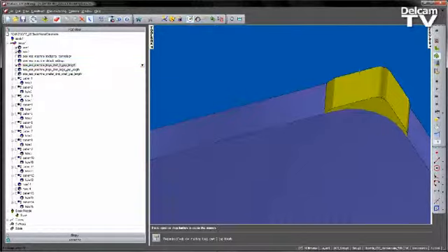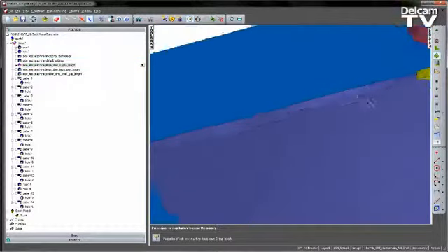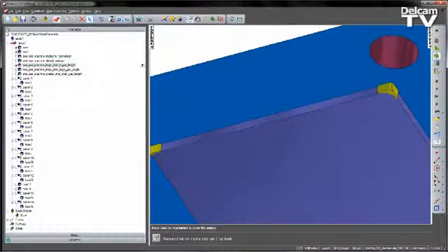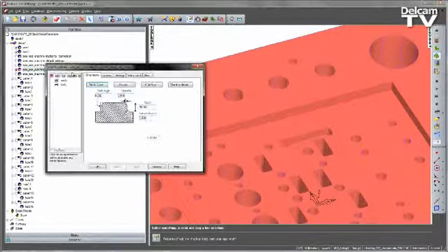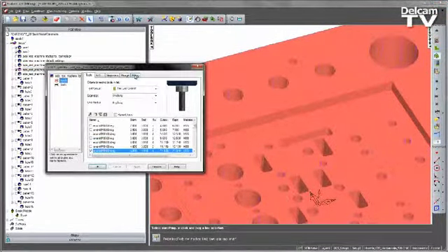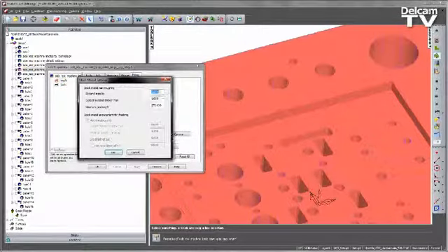So how do we force this finishing operation to work its way all the way around the component whilst maintaining the efficient machining on the roughing? Well, we could use, in this example, the next option. It's under the milling, stop model options. We can drop these values. So we've got 0 expansion, detect material thicker than set to 1, and in this case we've set a minimum gap length of 270 mm.